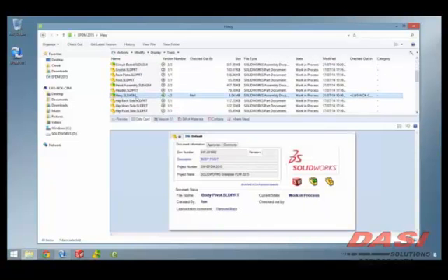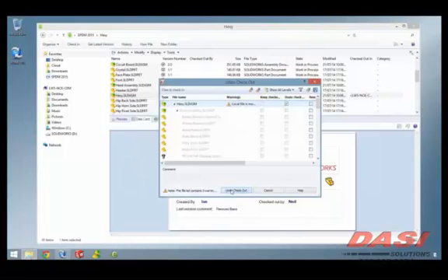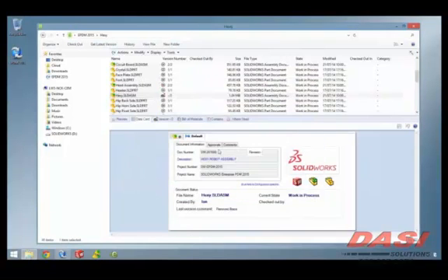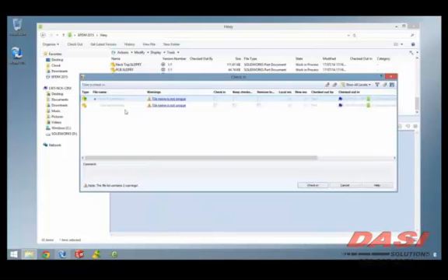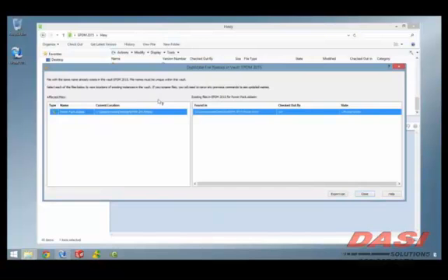So we can't check those files in. Let's just do an undo check out here. This is going to flush our assembly back to the original version. So within its tree now, it's going to get rid of the connector and that top-level assembly. Now we have a version column that actually shows us the details based on icons here in the Windows Explorer view, not just in the SolidWorks view. We still have those two files within the vault. If we try to check them in, it's going to give us a nice error message, but this also has a link to the duplicate parts file naming box.